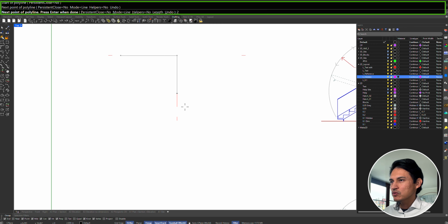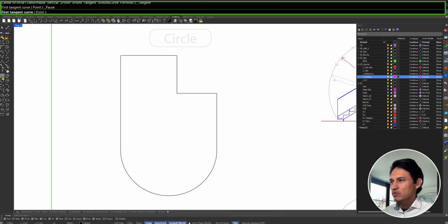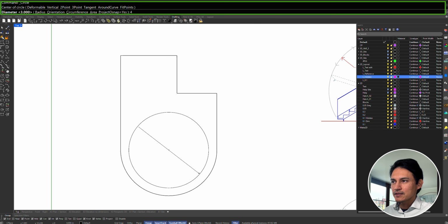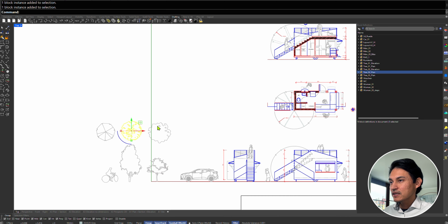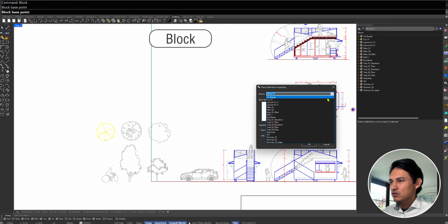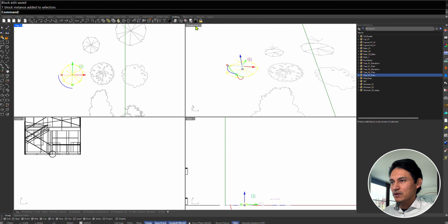Once you type the command, you will have some options to choose. Then go with the mouse to place the initial position, then set the direction and the next position, radius or second corner. To be more precise, you can also input numerical information according to the X, Y, Z coordinates in the command line. If you see that there are some elements that are repeating many times, like a type of window, tree, people, silhouette, cars, etc., you can also create blocks out of these 2D elements.